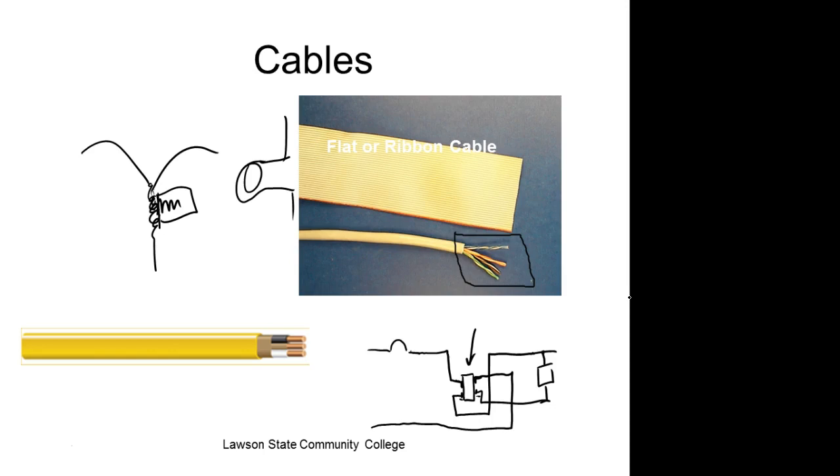So this is a network cable, a 100 ohm cable, and you can measure with an ohm meter all day long and you're not going to measure 100 ohms, because that 100 ohms is at a frequency. So if you come up here and you untwist those things to make them easy, you just screwed up because you changed the impedance of the cable.